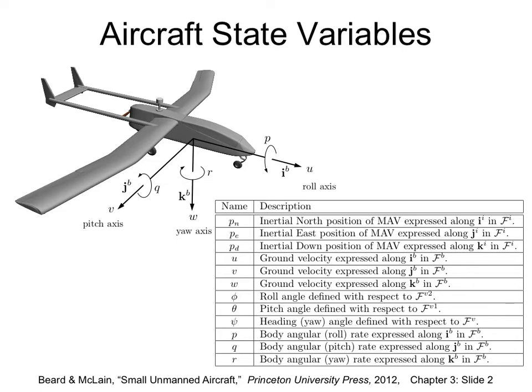These are conventions. The authors of the book have researched, and you will find that when you read other papers and books in the literature, this is the convention used. So when I say U, V, W, I will not have to say that this is the velocity vector of the vehicle; it's given. Phi, theta, psi, you already know, is the attitude of the aircraft: roll, pitch, yaw. And then you have P, Q, R. These are the new terms. P, Q, R are the angular velocity of the vehicle in body frame. How fast the vehicle is rotating about X, that is P, the roll rate; Q is the pitch rate; and R is the yaw rate.